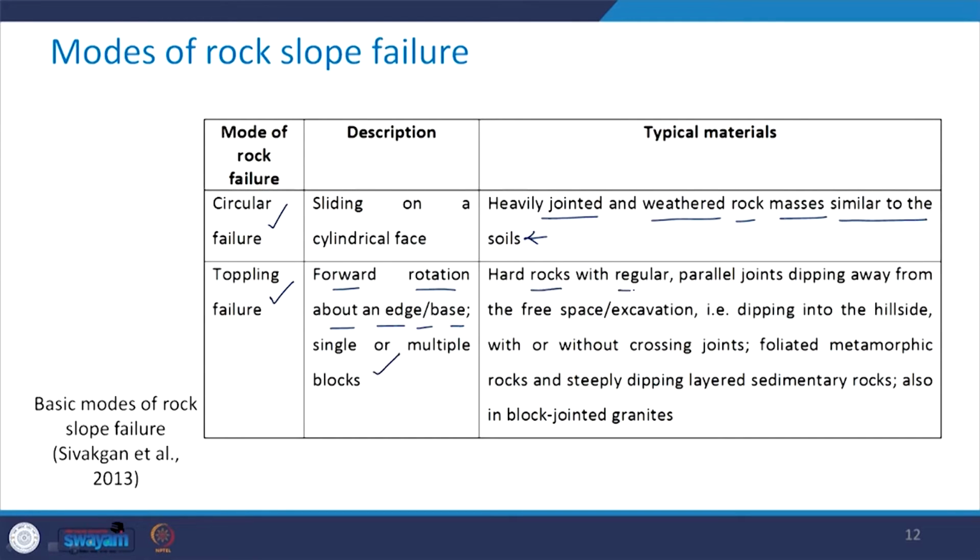Hard rocks with regular parallel joints dipping away from the free space or excavation, that is, dipping into the hillside with or without crossing joints, foliated metamorphic rocks and steeply dipping layered sedimentary rocks, and toppling behavior is also observed in block jointed granites.